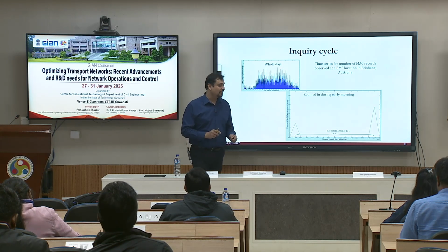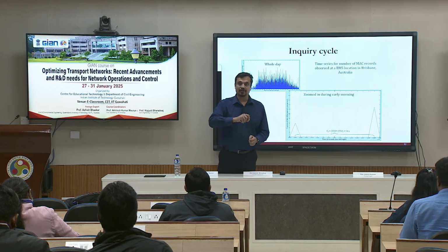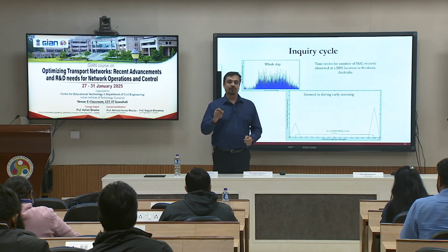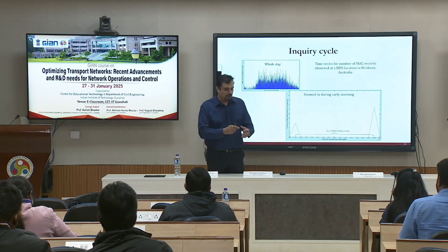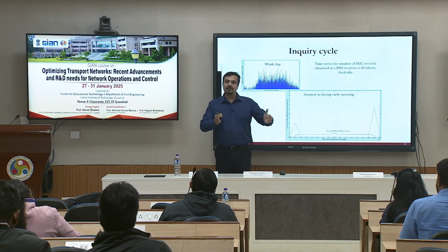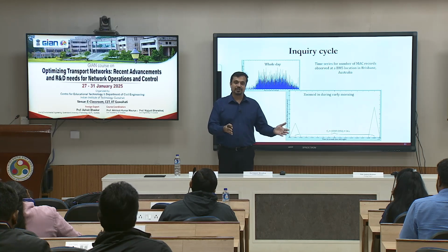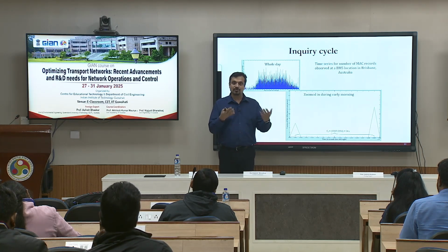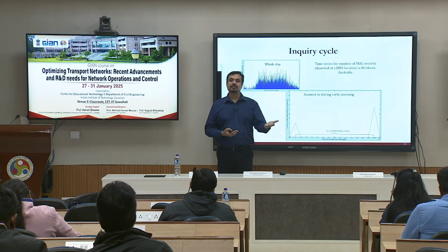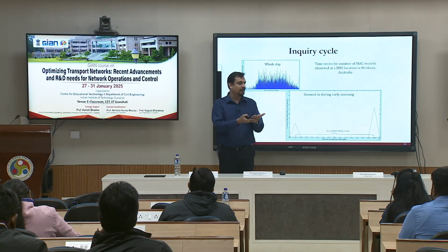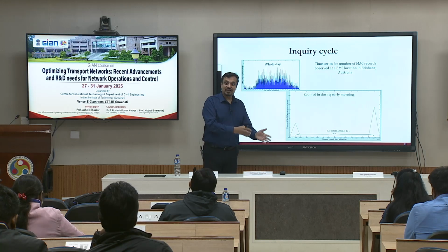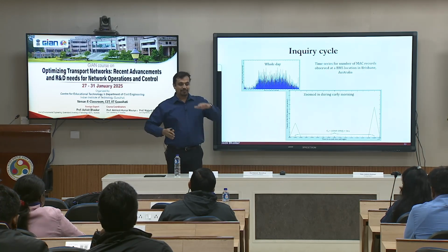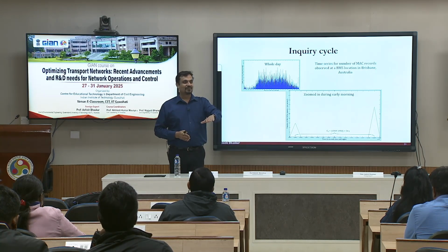That really helped us when I was doing an analysis for Main Roads Western Australia. They wanted us to study the penetration rate of the MAC addresses along the road. When you study the penetration rate on the arterial network, it's a good penetration rate because your traffic is less and you're observing more. Let's say you are observing 15 MAC addresses and the traffic is, let's say, 100 vehicles, so 15%, just for number's sake. But when you take the same thing on the motorways, the penetration rate was just 3 to 4%. Why?